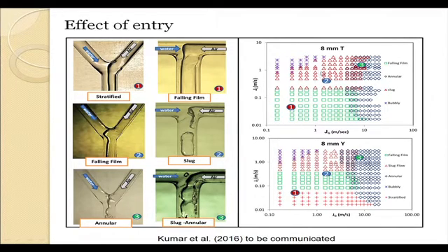If you observe, we have obtained slug flow pattern in this particular case. On the other hand, if you observe the Y, we find that the pinching action of the water is not sufficient, because the water has to climb against gravity and then pierce the air, which is not possible. So in this case, it has just transitioned from the stratified to the falling film flow, and so while it is slug here, it is falling film in this case. At still higher velocities, what do we find? In this case, it is a slug annulus sort of flow. There is a transition, because the bridging action of the water phase still works, and it tends to break the long gas core periodically, or it bridges the continuous gas core, whereas for the Y junction the flow is more or less annular.